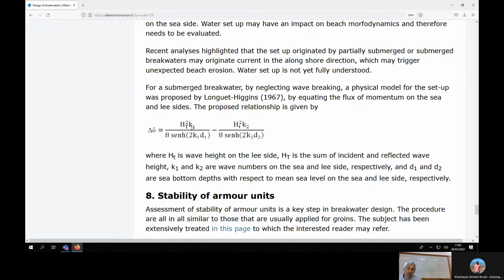And in order to mitigate it, of course, you solve one problem. On the one hand, you solve the problem. On the other hand, you have a side effect. And the side effect is to be considered among the other side effects. Another side effect is water pollution, because, of course, in the lee side, you have a calm situation, and then you cannot remove pollutants. But this is interesting because it's something that you wouldn't expect. It's not immediate to get that you may get this longshore current, which depends on the situation if it's important or not.